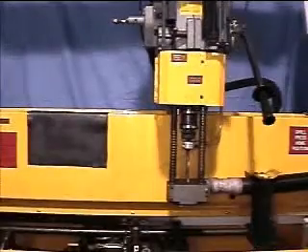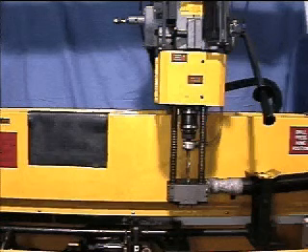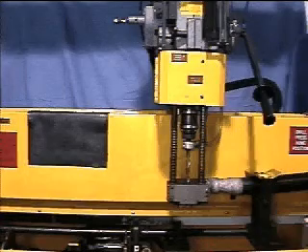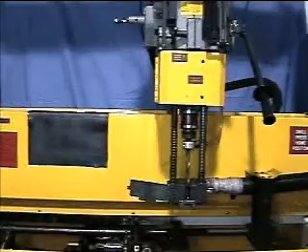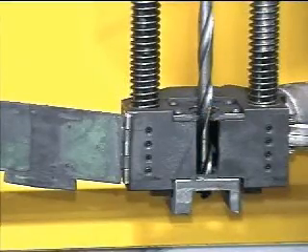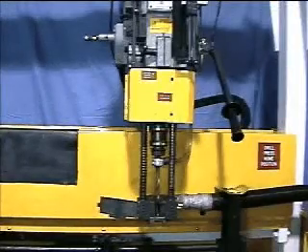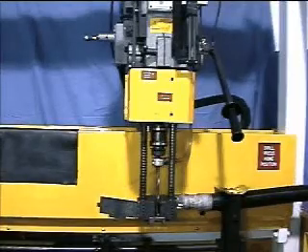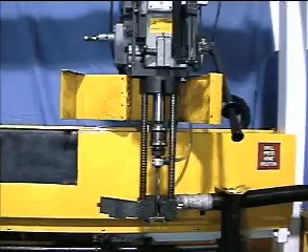The chip evacuation system is made up of 4 components. 1. The vacuum block. 2. Quick disconnect drill holder with a rotary coolant coupling. 3. Easily removable lower vacuum drill bushing. 4. Spring-loaded slides. This system is connected to a standard Clausing 20-inch drill. The guard moves out of the way easily for drill maintenance.